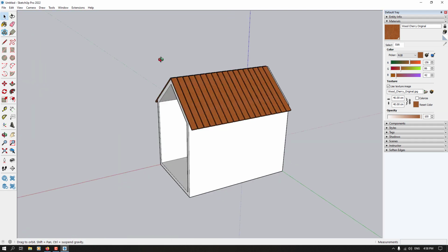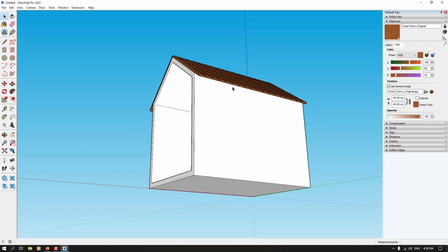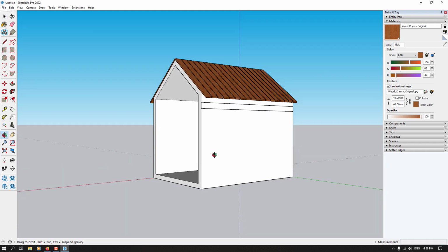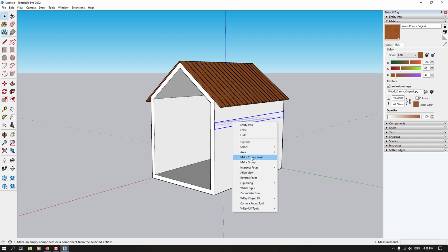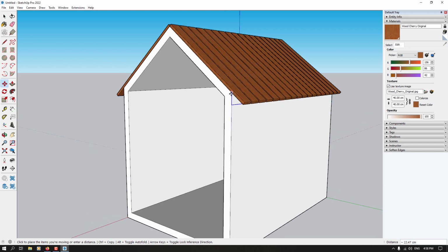So for the main body we can repeat these lines again, but I want to repeat it in the horizontal direction like this, and I'm gonna type some number about 7 to the 146. Now I'm gonna make a component of it again, so I'm gonna place it in this place, and now I'm gonna reduce the height of it about 10 and make some copies of them.